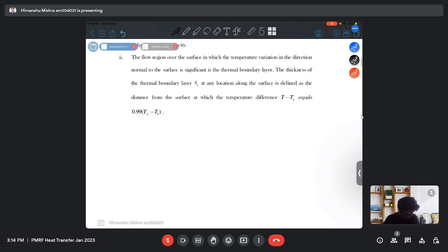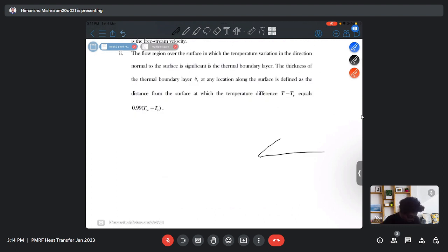This is a correct statement because we usually define a hydrodynamic boundary layer by the normal distance, the boundary layer thickness, defined by delta. This distance extends up to where the velocity of a fluid parcel is approximately equal to the free stream velocity V. To be more specific, we usually take the velocity of a fluid parcel at the boundary layer edge to be 0.99 of the free stream velocity V.